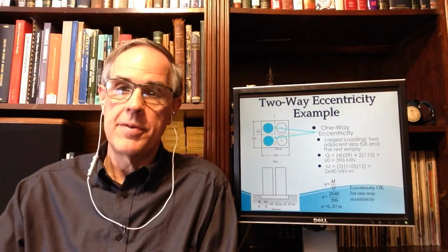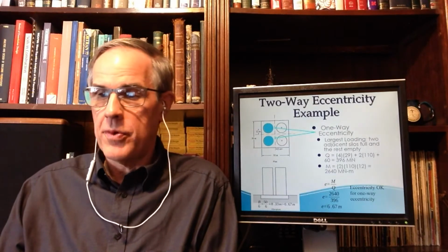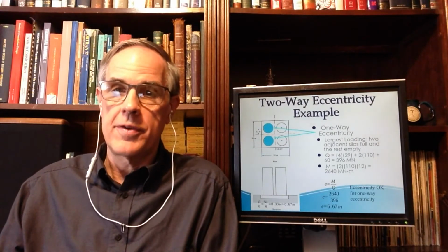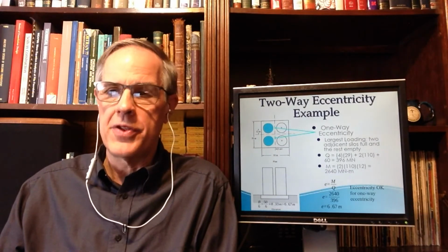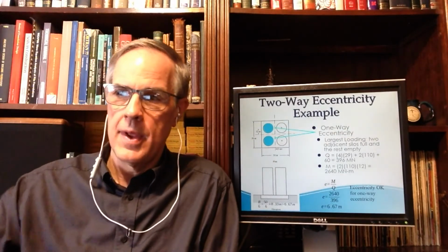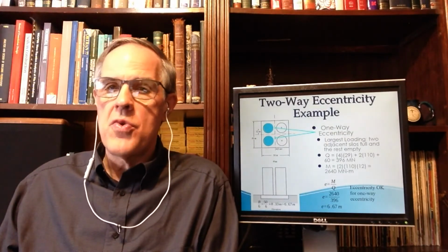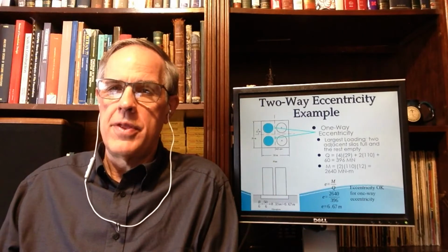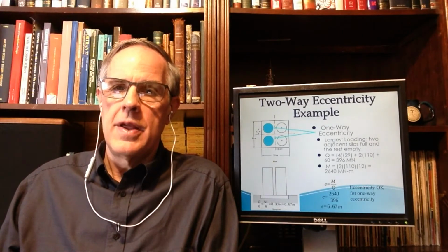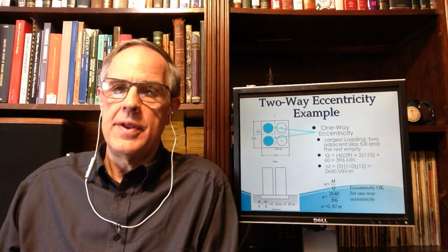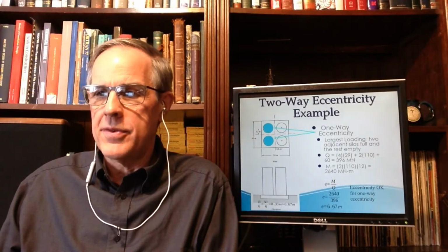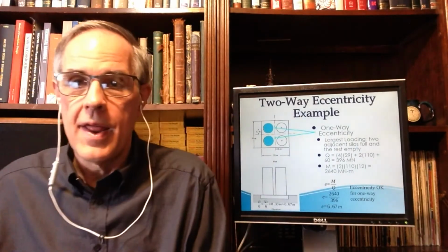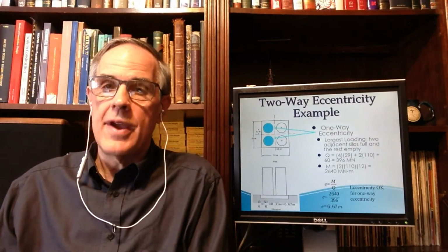The maximum eccentricity is 8.33, which is greater than 6.67. So we're still in the middle third on that loading. Now you would think that this would be the worst case, the conventional wisdom would say that, well, that's the most because you've got the load over on one side. That's not the case, however.